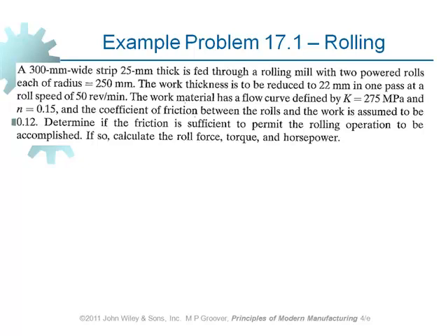How can we increase friction? By removing any lubricant or something which plays the role of a lubrication, or by making the surface of the material rougher, which isn't often needed. So if a material is well lubricated, it plays a negative role in the rolling process because we are lowering the friction.